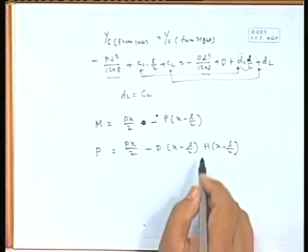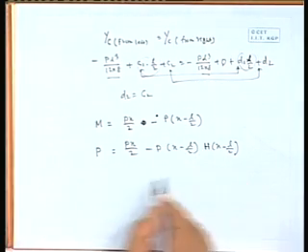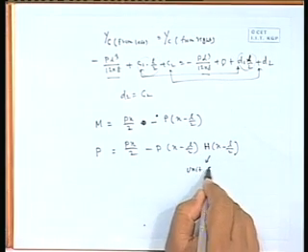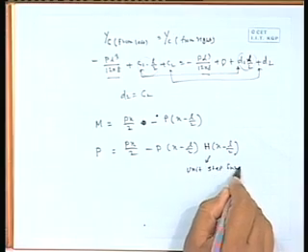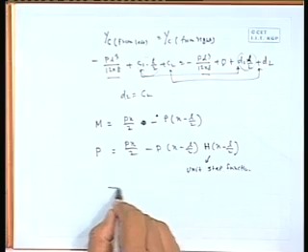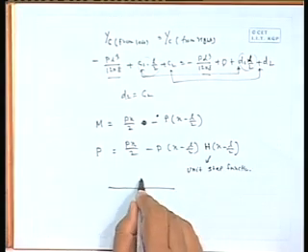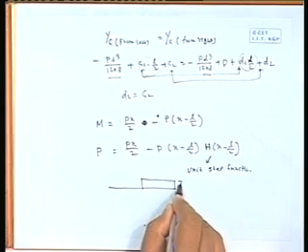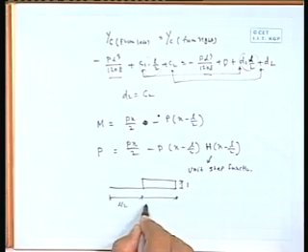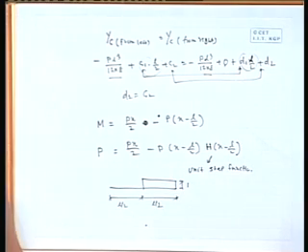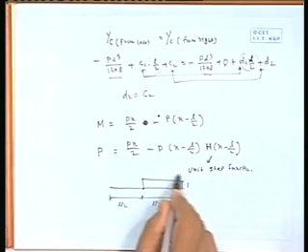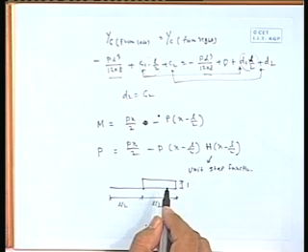Okay. Now, this h(L minus x), this is called unit step function, and its value is something like this. Here it is 1 unit, it is L by 2, it is L by 2. So, up to there it is 0, then it will be 1, right.